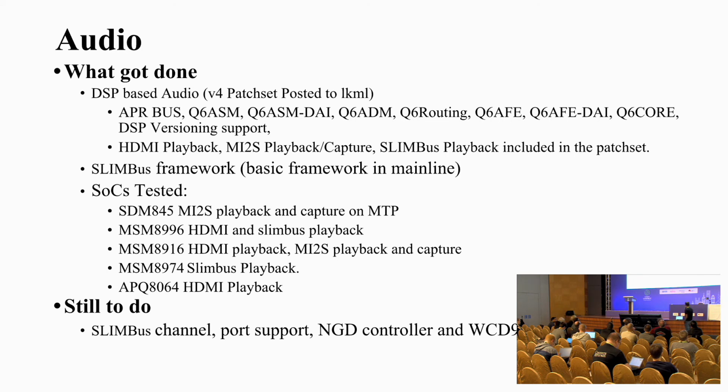Okay, down to audio. I think Srini has been working on the ADSP-based audio for a while now. Yeah, I posted a patch set a few weeks back with Mark's comments addressed. So far what we have in that patch set is basic playback and record support on multiple interfaces like I2S, HDMI, and Slimbus, and it supports multiple SoCs as well. It's been tested on SDM845, 8996, 8916 and 8974.